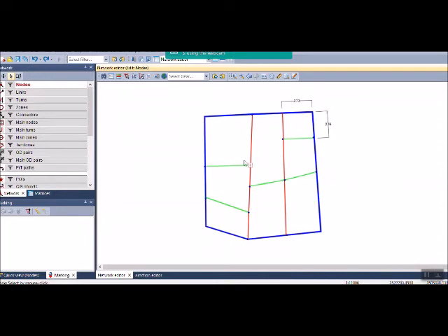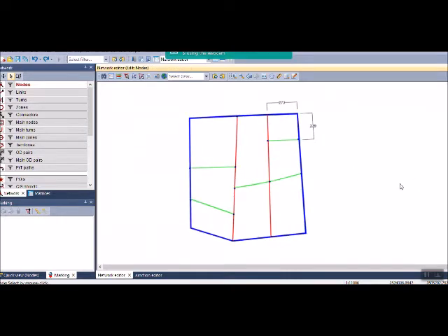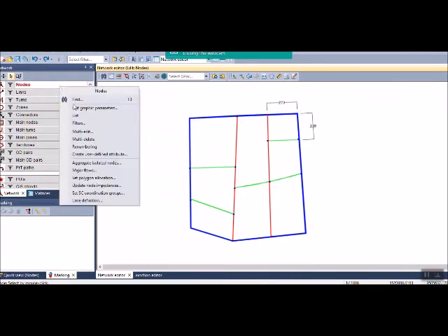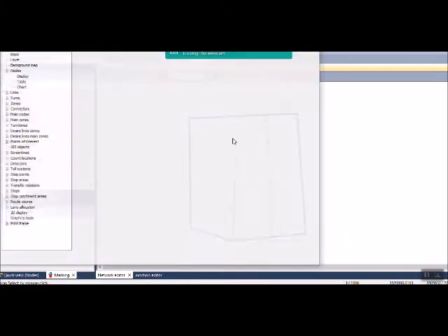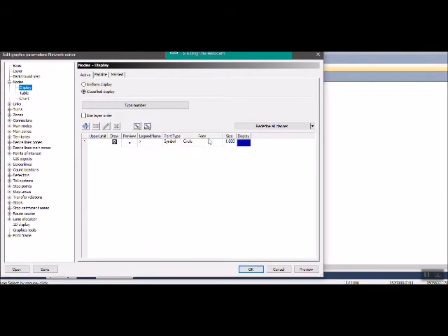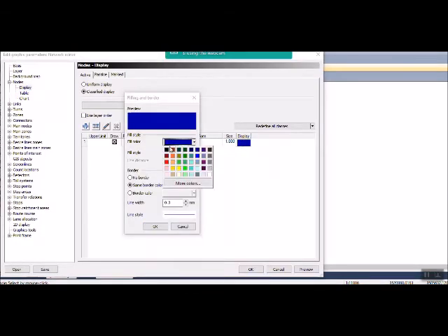We can change the display for it. I am going to skip the display, and we can do these things in a later video, but as a quick guide, anything related to the display, like the colors and these things, you can do from the graphic parameters. So we are going to go to the nodes, right click on it and choose edit graphic parameters, and from in here you can change, for example, the color.